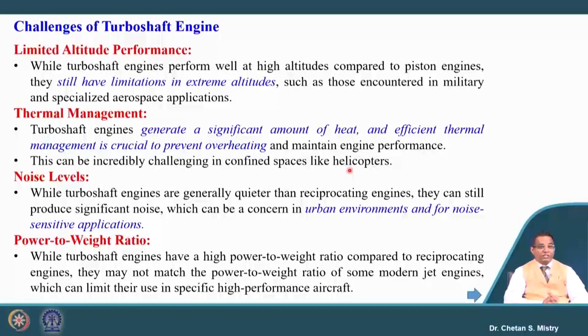Same way, when we are discussing the noise level, as we have discussed, the noise level is lower compared to other engines, but when we are talking about the urban environment as well as special applications, these helicopters are making a lot of noise. And the power to weight ratio, as we have discussed, compared to our reciprocating engine, is the best, but when we compare with the turbojet engine, there is trouble in terms of the higher power to weight ratio of jet engines.